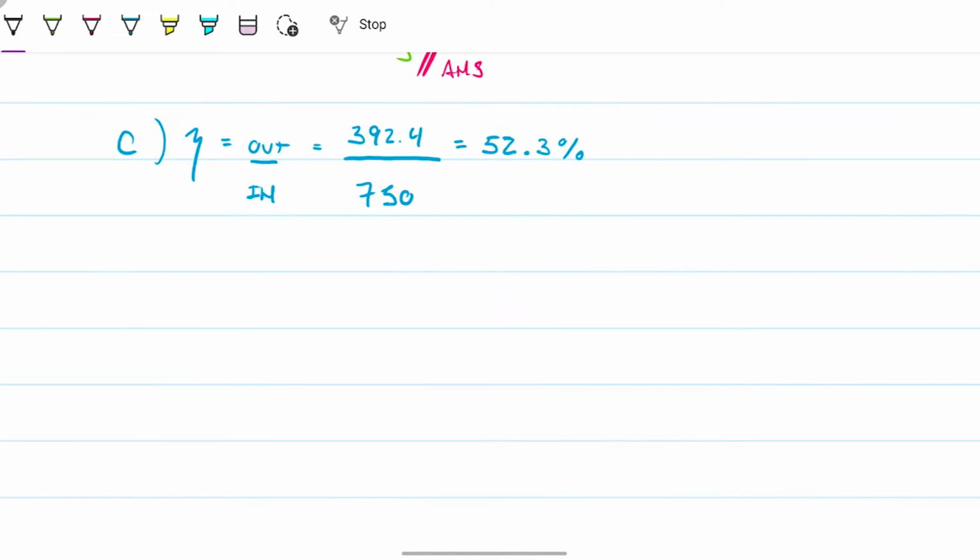And then last, probably the most weird or most different part of the problem is, what is the mean effective pressure? And we talked about how this was just work divided by volume. It's just an assumption that we can get one single pressure for the whole cycle, which is not the case, and then what that would look like. And here we have the volume.